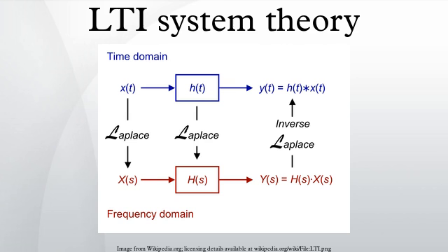Exponentials as eigenfunctions. An eigenfunction is a function for which the output of the operator is the same function, just scaled by some amount. In symbols, where f is the eigenfunction and λ is the eigenvalue, a constant. The exponential functions, are eigenfunctions of a linear, time-invariant operator. T is the sampling interval. A simple proof illustrates this concept.